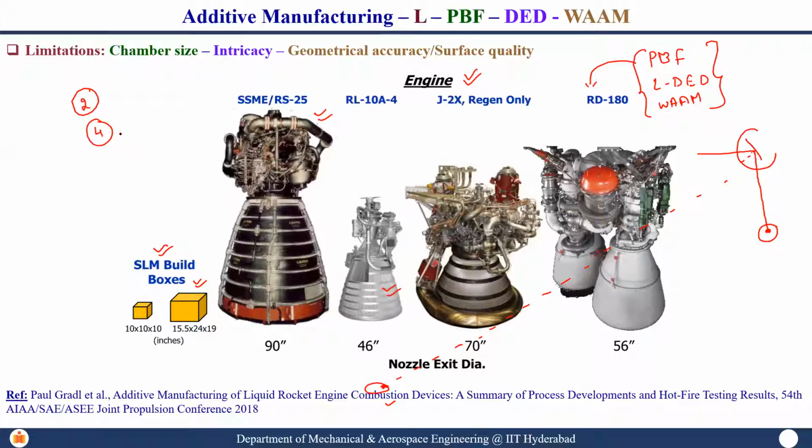As of now, there are a few companies producing with quad lasers, so that this issue of focusing the laser beam at a farther place is reduced. So this is the limitation. Ultimately, right now we have only two options when we go to large area additive manufacturing, that is DED and VAM.